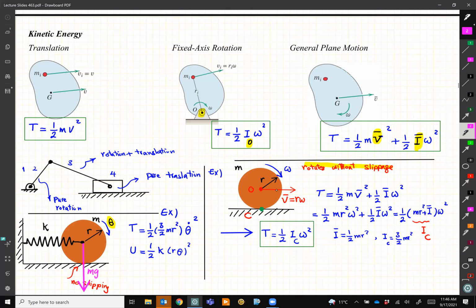We had this rule that we look at the equilibrium position and see if the mass deflects the spring when we are at the equilibrium. Is there a static deflection in the spring? If there is, since they are going to cancel out each other, we don't include it into the equation. But in this example, there is no pre-deflection, pre-tension, or pre-compression in the spring because of the mass, right? So I should include it, right?